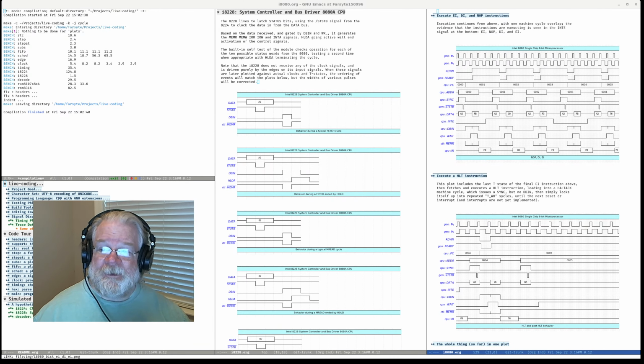Typically, you want to enable interrupts and halt, and then somebody does something. They will interrupt you, and they will send you an instruction to execute. And typically, that will be a RST instruction, which is a 1-byte instruction that will call to one of 8 addresses in low memory. Or you can actually send a call instruction in the real hardware. And I'm going to have to work out how to make that work in the software.